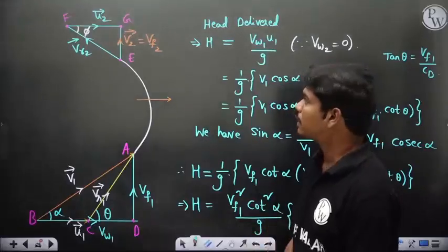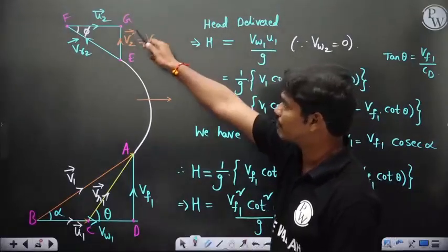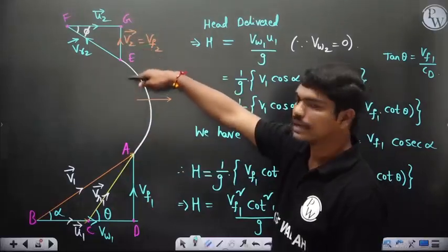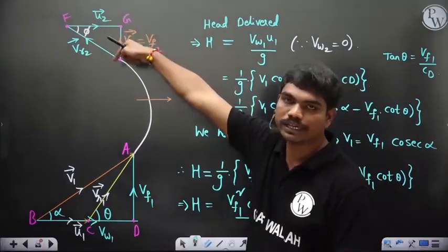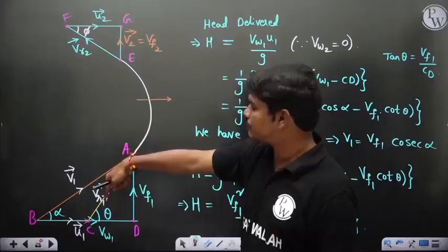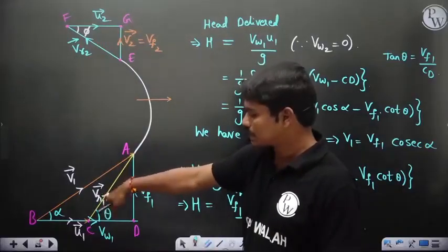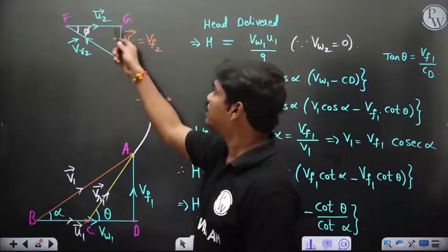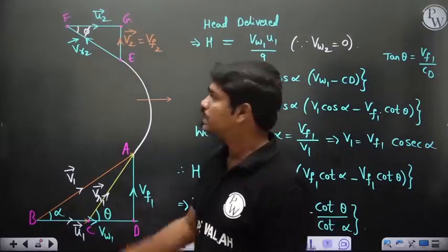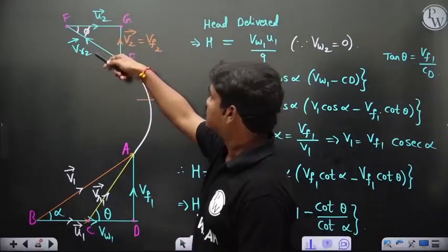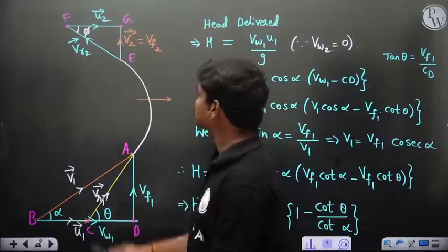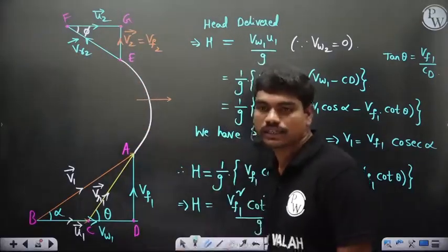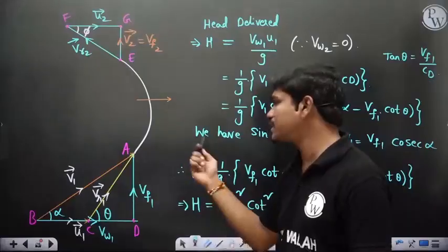Okay, also one more thing is you can also relate that phi. How come? This Vr1 can be replaced with Vr2, because if you want to bring in U2 into the picture, you can relate Vr1 equal to Vr2. So whatever expressions you have for Vr1 here, you can replace with Vr2 expressions. For example, Vr2 sin phi is Vf2, so Vf2 is equal to Vr2 cosecant phi. So you can relate the things again. Using all these things we can calculate.